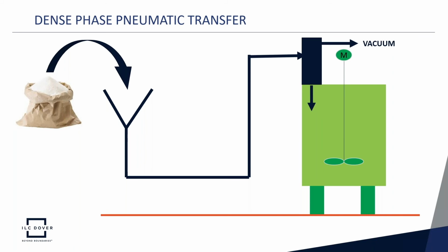The methods required to achieve high powder recovery complicate the system and the subsequent cleaning of it. Fine dosing arrangements are available, but these are typically not successful when one system is used for multiple powders. The second drawback of dense phase powder transfer is the space needed on top of the mix tank for the chamber required for the gas powder separation.